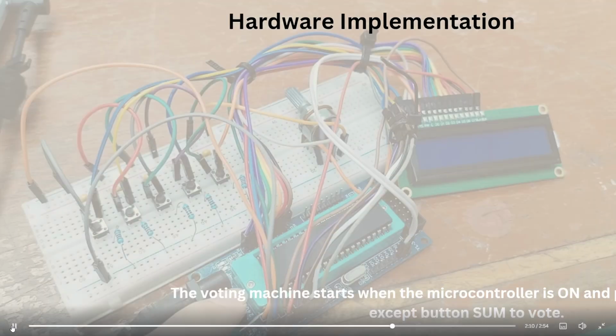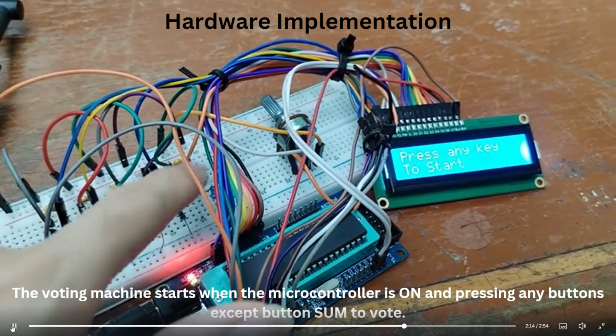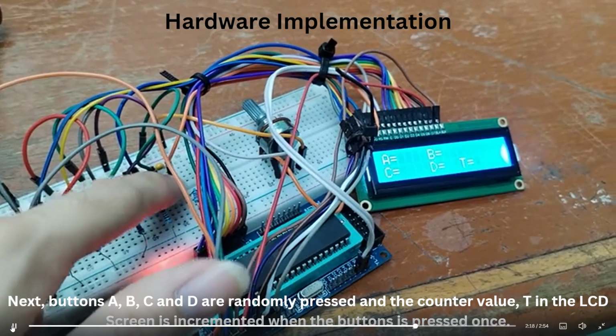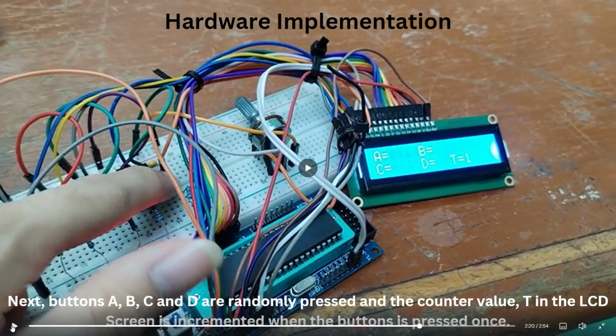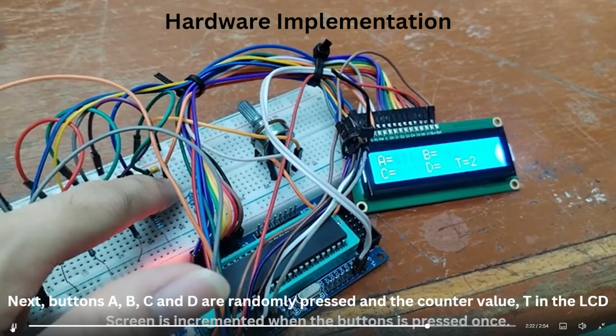And it's time for the hardware implementation. The voting machine will start when the microcontroller is on and any button except the sum button is pressed. Next, buttons A, B, C, and D are randomly pressed, and the counter value T on the LCD screen is incremented each time a button is pressed once.